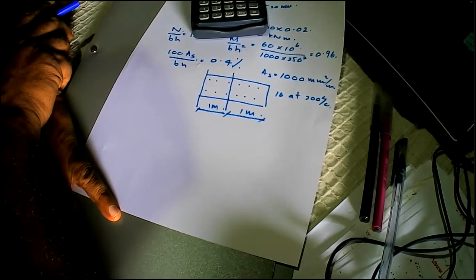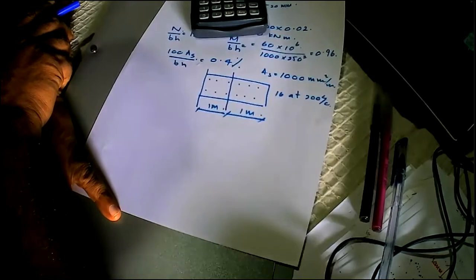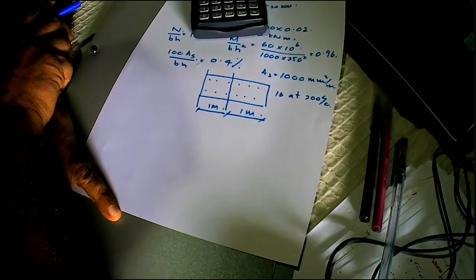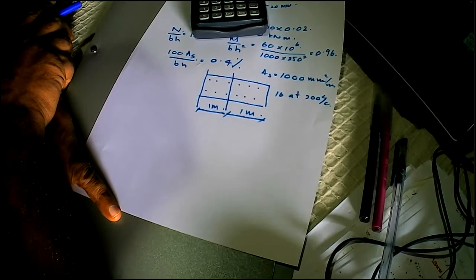That's why we have to make sure that reasonable load is transferred onto the shear wall, reasonable vertical load. So we don't like a shear wall that is not supporting any slabs, because if the shear wall is supporting slabs, then at each floor level, the slabs can transfer a certain amount of load onto the shear wall, and that will stabilize the shear wall. Is that clear?